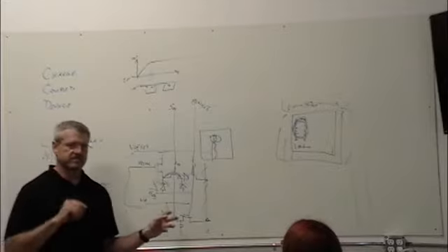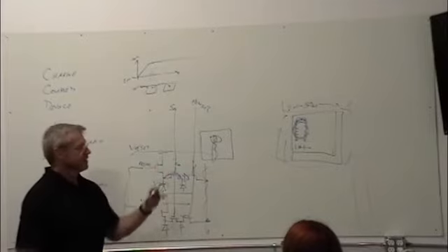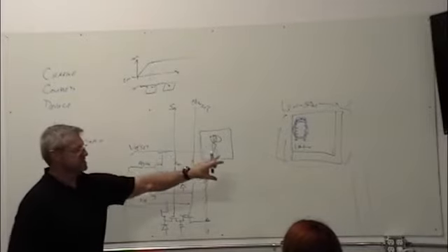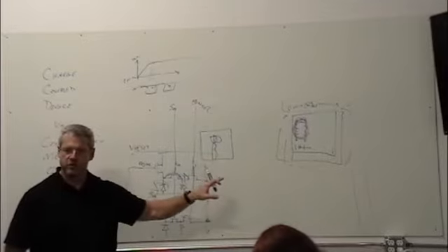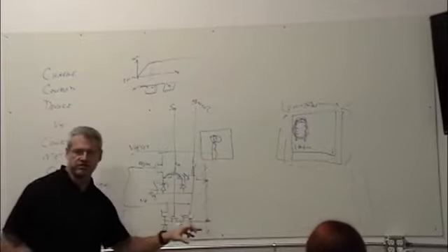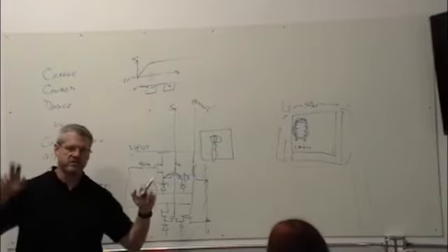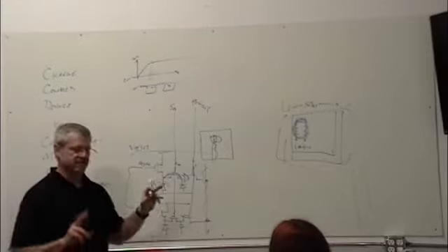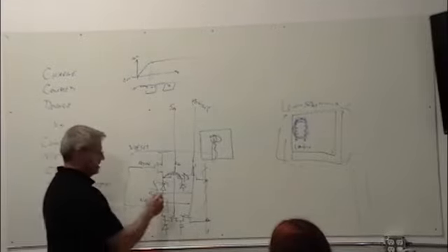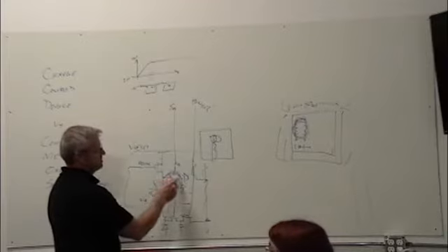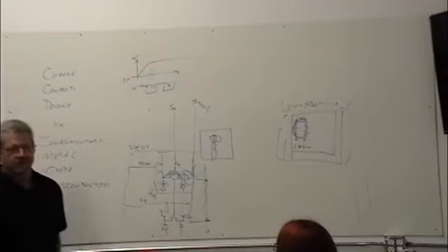Scientific CMOS does exist. They've gotten very good. Because the CCD sensor itself is so low noise, what sets your noise floor is your first amplifier coming out, just like for an RF signal chain. Whatever noise figure isn't the phrase that's used, but it's that one right there. Your noise floor might be set by that switch, but that amplifier right there sets your noise floor.